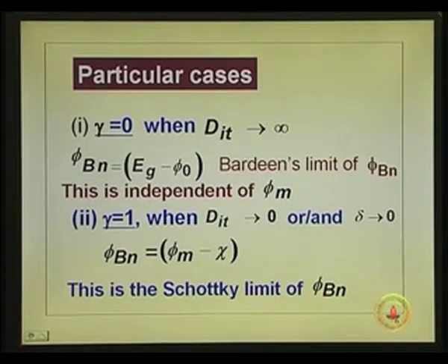Phi naught is actually the energy gap between the neutral level E naught and Ev. Okay. So, that depends upon the particular material, the surface condition of the material and actually the material. For gallium arsenide and silicon, it so turns out that phi naught is about 1/3 of Eg. If it is 1/3 of Eg, then this whole thing will become 2/3 of Eg. We will take a look at that further.